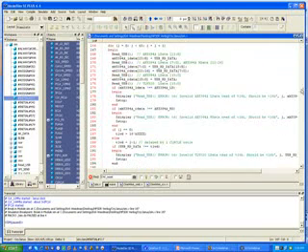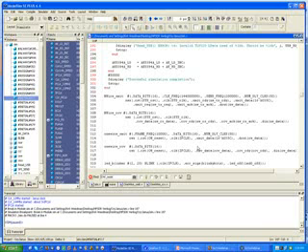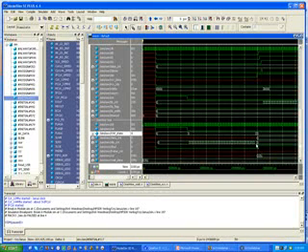Let's go back down. Okay, right here I said num delay clocks is 50, so I overrode it just so it wouldn't take forever, because normally this would be a very long time. I overrode it just for test purposes, because all I'm doing is testing. Normally it's going to take like 200 milliseconds, and I don't want to wait 200 milliseconds of simulation time. So I said, okay, just 50 clocks instead of millions of clocks or whatever it takes. And sure enough, that's what we got here, a value of 50.